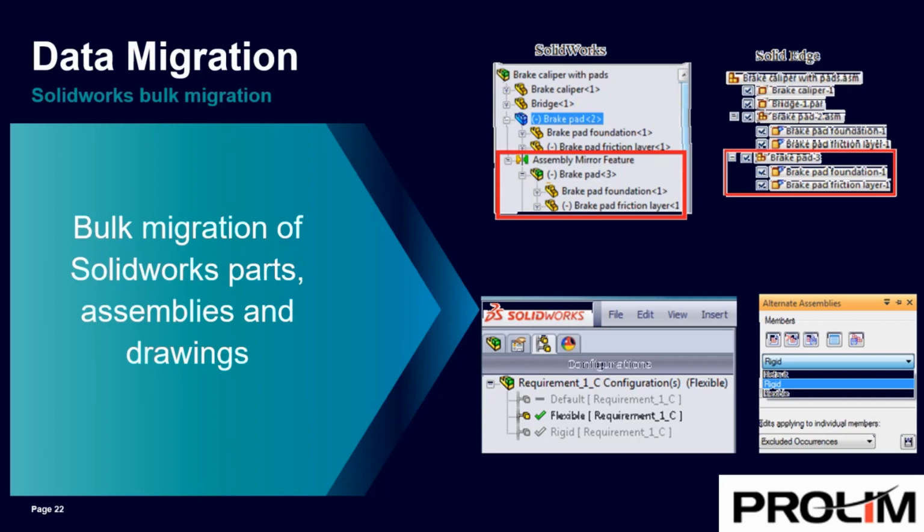I will state that configurations is a funny buzzword because the different softwares consider configurations two different things. I'll just briefly explain that here. Even though they both have configurations, they have different terms for them. In Solid Edge, the term configurations is used to display different design configurations or display states of an assembly, maybe a different isometric view with a couple of parts either hidden or suppressed or in a different position. That's what Solid Edge considers a configuration.